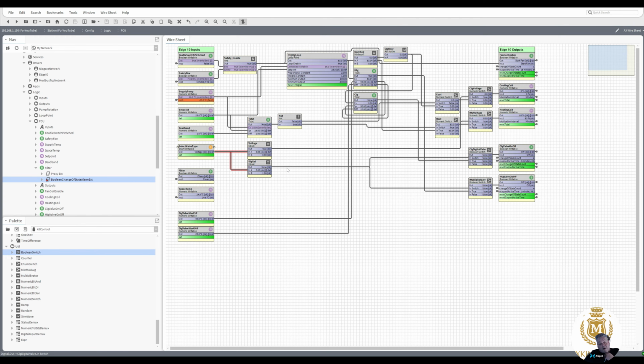Mostly with fan coils, they are not 10 volt control, so you will probably find a cooling coil and a heating coil with 0 to 10 actuators on. This will probably be very rare. You probably wouldn't use this at all, but we're just given an option for using an on and off, open and closed valve, but very rarely you will see that.